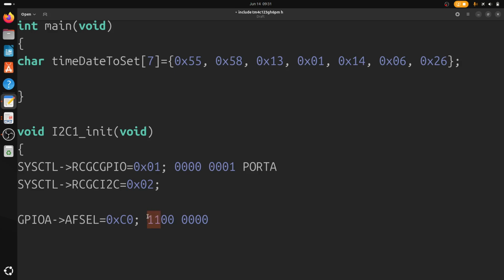We choose these pins 6 and 7 because alternate function means we can use them for any operation, for I2C, SPI, UART, anything. And we are choosing only 2 pins, because one is for SCL and one is for SDA, and we need only 2 lines. I2C is a 2 line bus, so because of that.